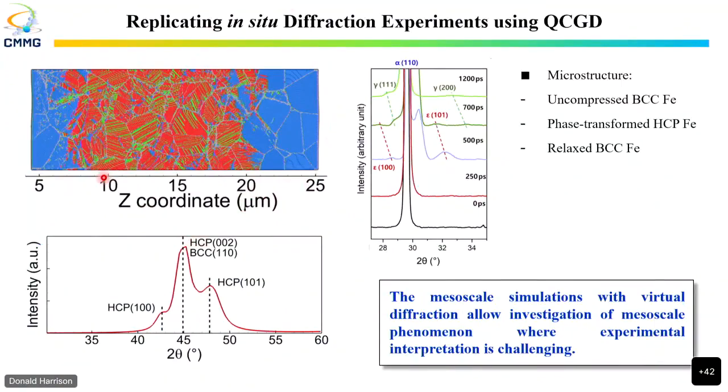And you can look at this as, okay, this is maybe 0.5 nanoseconds before breakout, or this is 0.5 nanoseconds after breakout, and you can start correlating how much of the peak broadening and how much of the peak shift is because of that, and how much of the peak shape is because of contributions from the stacking fault, or the contributions from the twins in the microstructure. So that is the analysis we are doing currently. We're building machine learning models to correlate phase fractions and defect fractions to the actual diffraction patterns. This is an effort that's going on with Remy at Sandia.